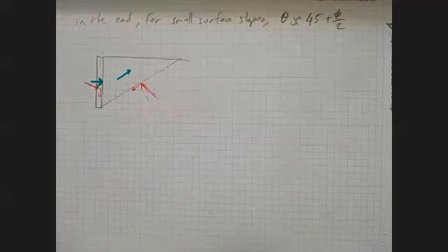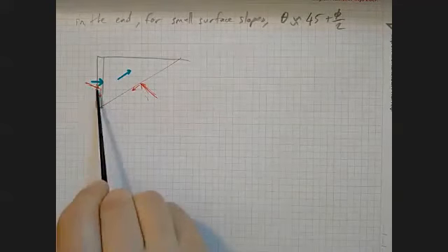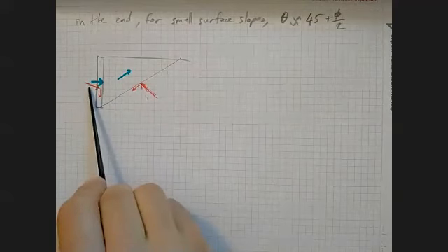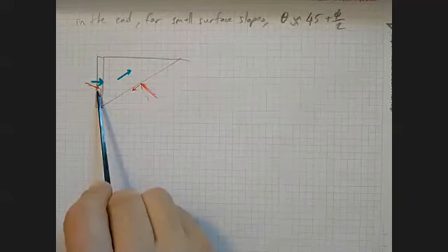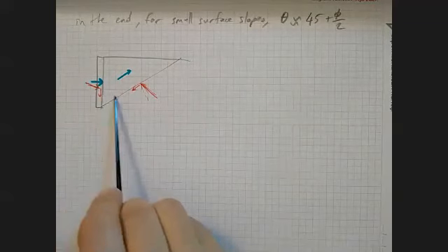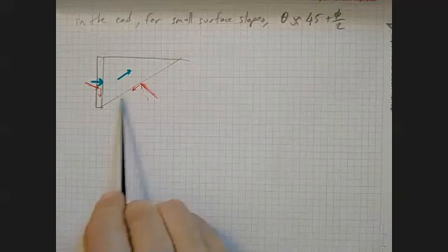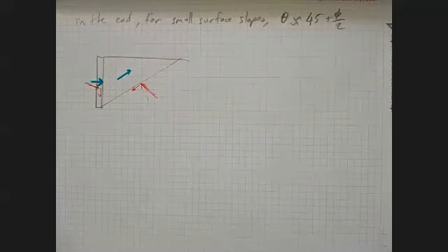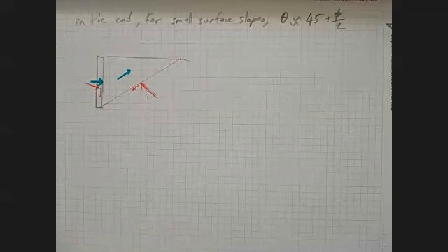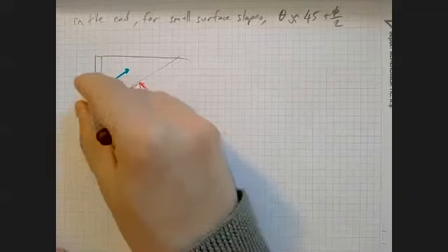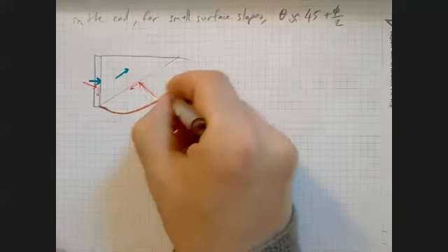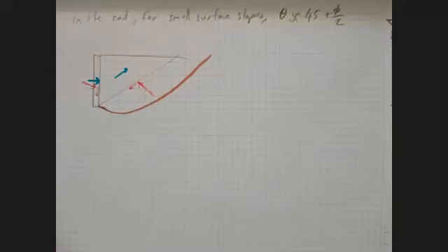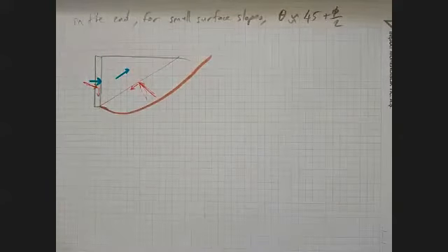The reason for that is because your passive force in the wall is downwards, and it is pressing directly towards the failure surface. So what in reality happens is, you get some failure surface like this that is actually more critical than this line. It's counterintuitive, because now you are moving even more soil,